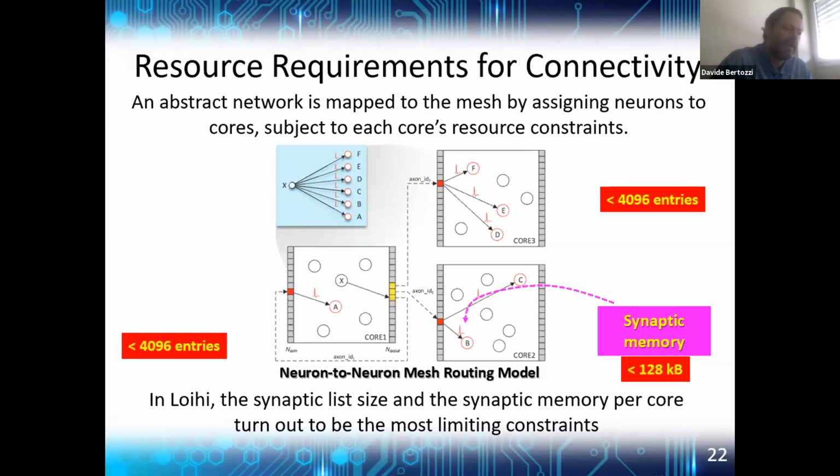It has on-chip learning capability, done on-chip and autonomously by this chip. So given a particular neuron to core mapping, each neuron's synaptic fan-in state must be stored in some memory. This adds up to the core's synaptic memory. The state of the synapses is stored in this synaptic memory, and this is the first memory requirement of the system.